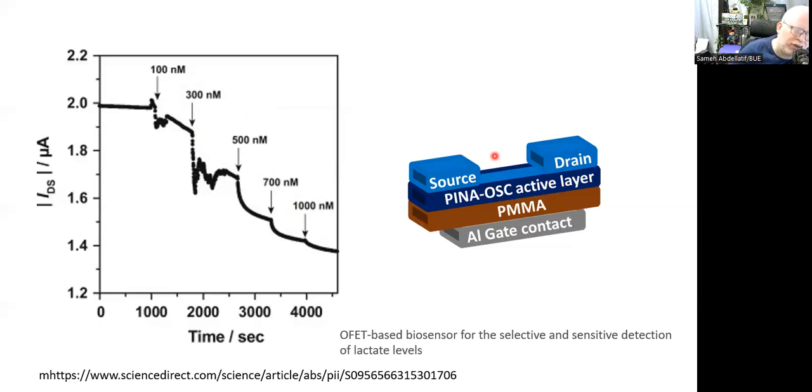when you have a P-type material and you make an N-doping, that means that the N-dopant will combine with some of the P, and that will reduce the total number of P. So whenever you increase the concentration, the doping decreases, and then the conductivity decreases, and then the current decreases. This is how I can understand the process, again, from an electrical perspective. This is, of course, not the correct way from a chemical or from a biomedical perspective, but this is just for giving a focus from an electrical or electronic perspective for biomedical sensing.